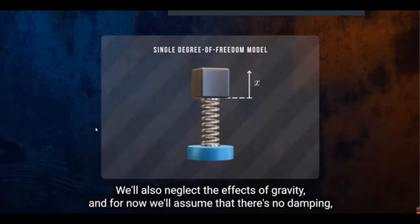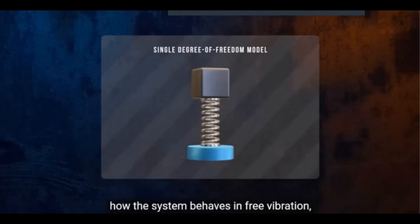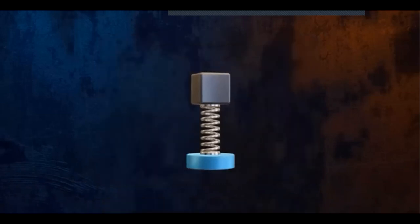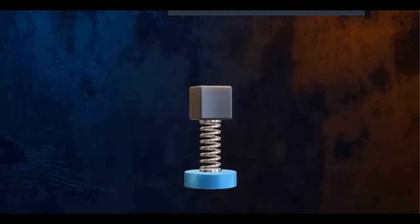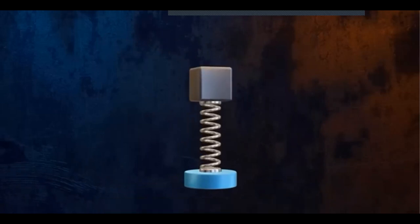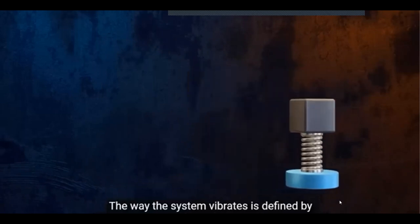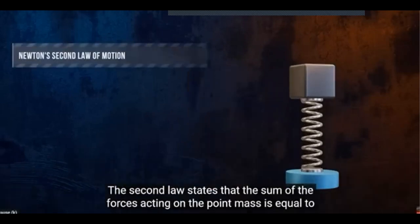Neglect the effects of gravity. And for now, we'll assume that there's no damping, meaning that no energy is lost from the system as it vibrates by friction or other means. No external loads are acting on the system. The purpose of the model is to understand how the system behaves in free vibration, or in other words, how it will oscillate when it's displaced and then released. Since we've assumed there's no damping, the mass will continue to oscillate like this indefinitely. The way the system vibrates is defined by its equation of motion, which can be determined by applying Newton's second law. The second law states that the sum...